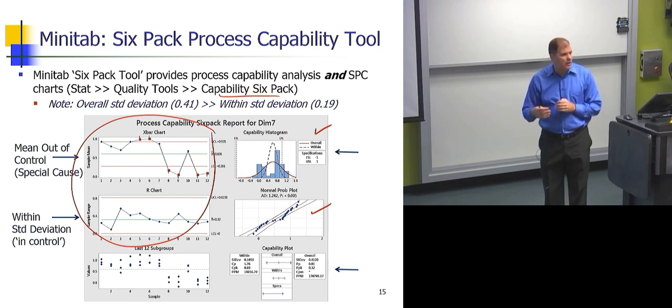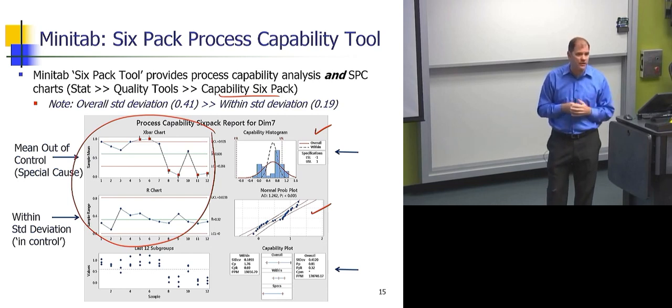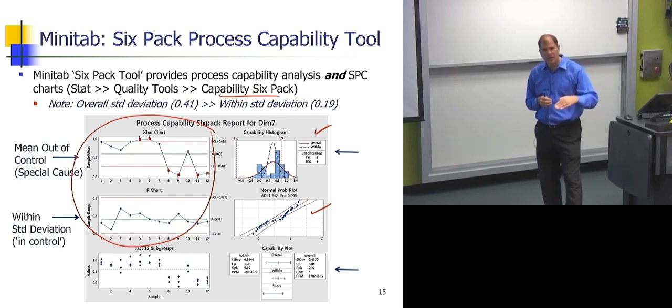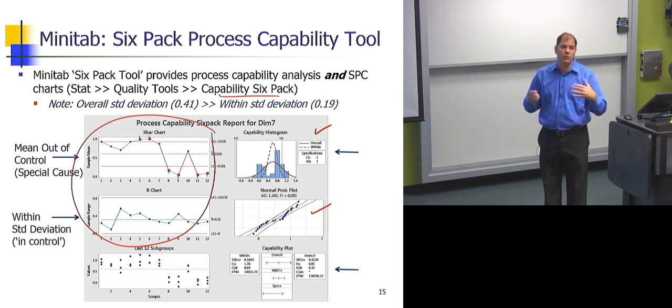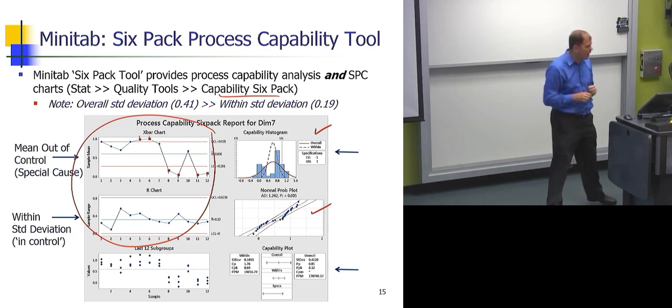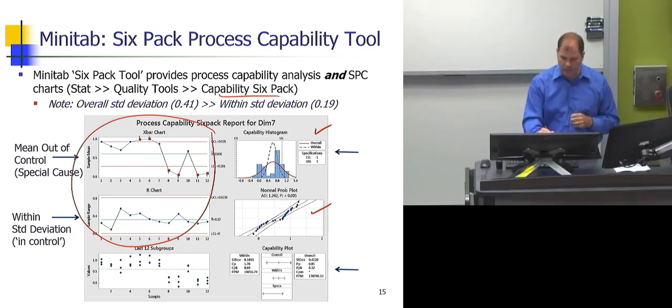No. CP is high. We have low common cause variation. It's not surprising to see that the range chart is in control. Common cause variation is low and stable. The mean is walking around, which is why sigma overall is much larger than sigma within.